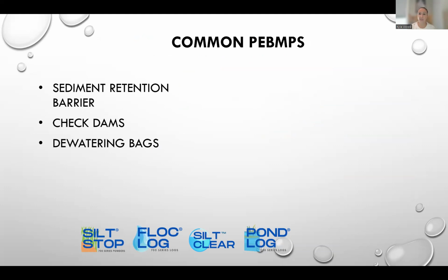It's basically a souped up silt fence, so we'll look at that in just a minute. I'm also going to talk about enhancing our different types of check structures with the flocculant, and then also a lot of projects are required to use dewatering bags or sediment bags. There are, I don't want to say right ways and wrong ways to use flocculants with dewatering bags, but we're going to talk about that because that's a pretty common BMP that we enhance using the flocculants.